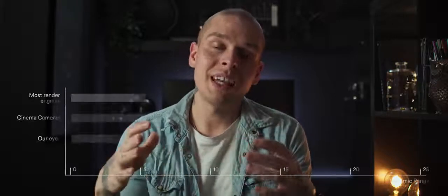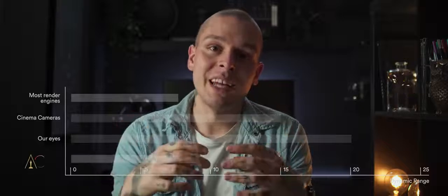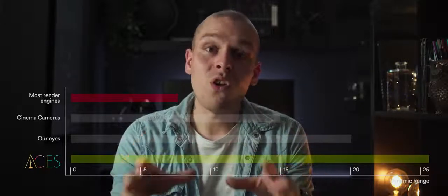A couple of words about biased render engines. ACES helps to make light look more realistic in those engines, because by default the dynamic range in those engines is quite low, and ACES expands it quite a bit. Octane is an unbiased engine, and the light behaves like real-world light straight away, so we don't have those problems other engines have. But still, it would be nice to actually render in ACES in addition to that and have that smooth, consistent pipeline. It's easy to overthink or overcomplicate all that stuff, but it's very straightforward, I promise.